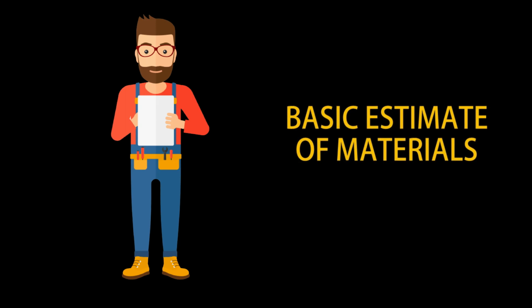In computing the required materials for concrete hollow block works, the estimator has to consider the following items: the quantity of the concrete hollow blocks, quantity of the cement and sand for block laying mortar, quantity of the cement and sand for mortar to fill the hollow cell of every block, the cement and sand required for plastering one or two sides of the blocks, the materials for CHB footing and concrete post as required.